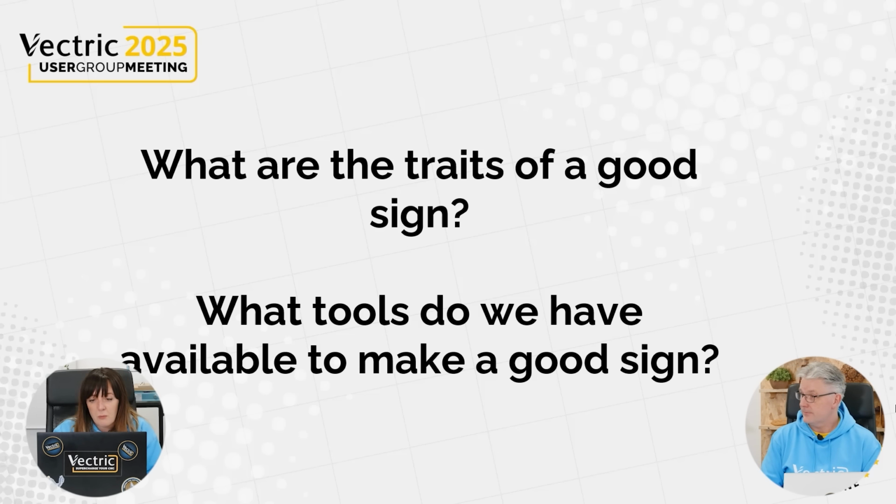Now I know I'd like this to be around 17 inches in diameter, which isn't the radius. We double that. What's really nice about all of the number fields in our software is that you can do maths in there. So if I divide that by 2, that should give me the radius, and then press equals and press enter. That should give me an actual 17-inch diameter circle. And if I'm sure of that, I can close this down, select it and press T on my keyboard, and you'll see right there the width and the height are 17 inches. That's perfect.